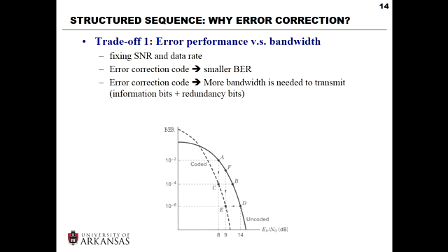And the same thing goes for channel coding. For channel coding, what we want to achieve is to minimize the error probability. The approach that we use to minimize the error probability is to add redundancy. If we add redundancy, we are wasting the bandwidth resources, right? So instead of transmitting, for example, 100 bits, we are transmitting 200 bits. So there is lots of redundancy in the channel, which means we do not utilize the channel as efficiently as a system that does not have channel coding, right? So that's a trade-off there. And we can look at this trade-off from different perspectives, okay?